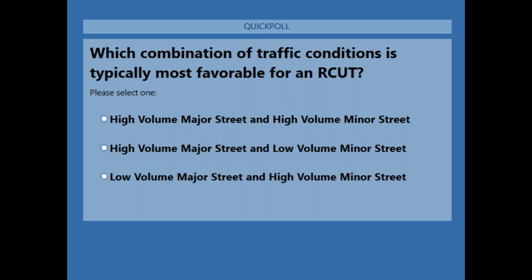Okay, for the super streets with 4 signals, do they operate off one controller? They can, yes. It's probably easier to do so. There are some agencies that choose to go with multiple controllers, but they can be run off of one. Okay, for the signalized R-CUT, does the U-turn need to be stop controlled? Theoretically, it could be yield controlled.